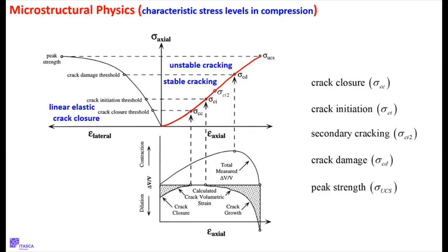So you need to load it slow enough that those effects aren't there anymore, meaning that if you loaded it even slower, you'd still get the same stress strain curve. This is what we do in the laboratory. It's really important.